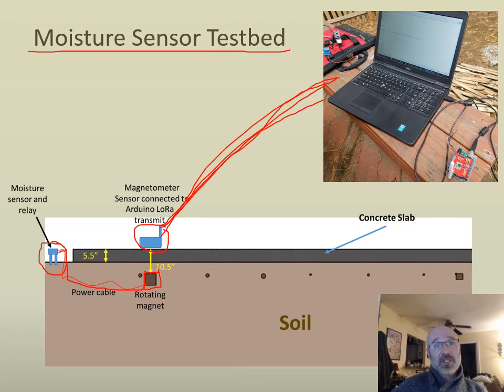Basically, the Arduino here is performing an FFT on our data that's coming from our rotating magnet, backing out a frequency of that, and based on the information we're getting from that frequency, we're sending that in very small data packets across the wireless LoRa network to our LoRa receiver over here, which goes onto our computer or our network right there.